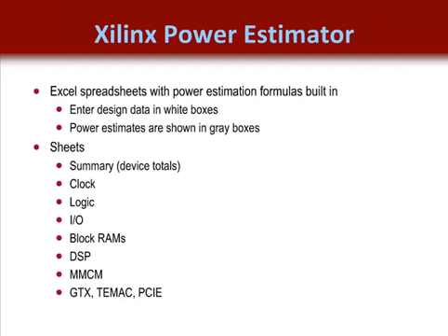In fact, ideally, you will target the dedicated hardware resources as much as possible rather than just use the CLB logic resources. This is because the dedicated hardware is optimized for minimal power consumption and high speed. So be sure you're getting the correct hardware resources inferred by your synthesis tool, since this will choose which resource to map to based on your HDL coding style, unless you instantiate a particular resource.